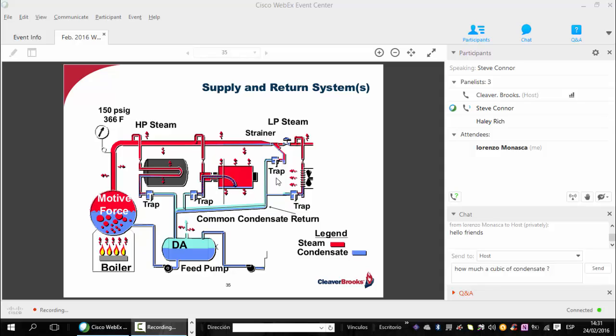And now going back to the total steam system slide again, you see drip traps at various locations feeding into the common. And they are all at different temperatures depending if the user was at low or high pressure when the condensate was trapped. This is how biphase flow is generated, because it is the amount of flash steam generated as a result of the difference in temperature between the trap's discharge and the condensate line's temperature and pressure.